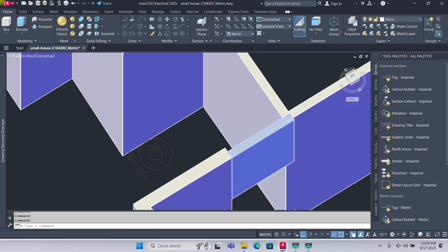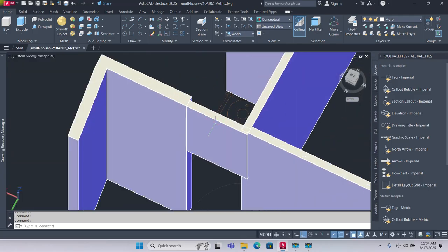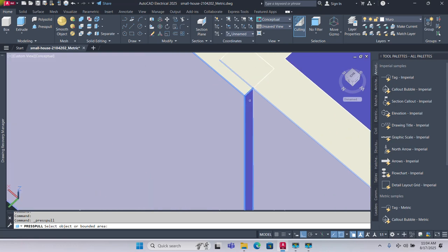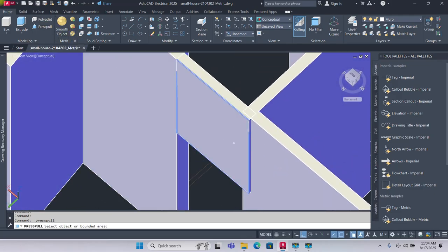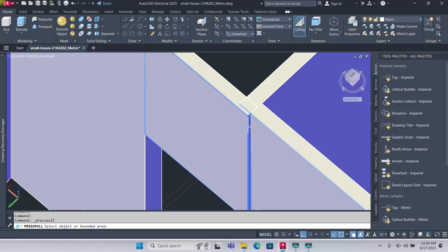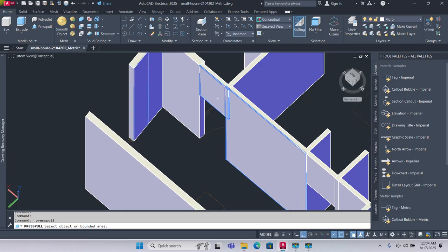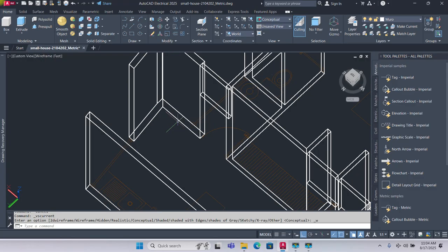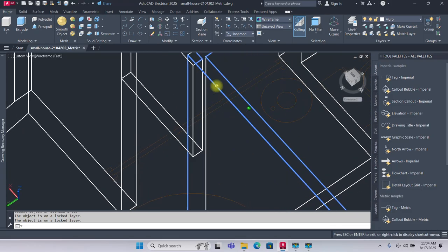This one is actually good, but the only problem is, you notice the width is not the normal width for this, but it's not a problem. We can just use our press pull to select the face of this and then press pull it in. All right, so that's what we will do. So let me wireframe, press pull, come to this face right here.